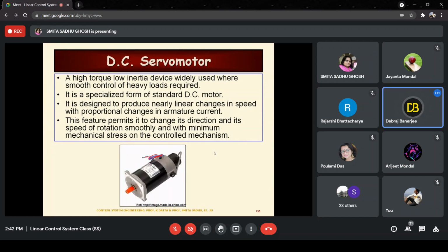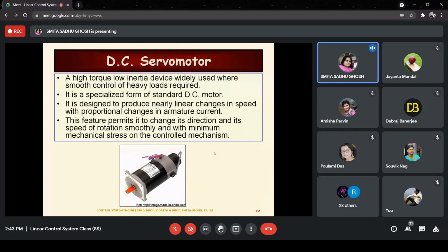Proportional to radius square. Yes. So if we want a lower inertia, we should typically make the radius big or small? Small radius. Yes, small. That's obvious, isn't it? So the radius we would want to keep small so that the motor has a lower inertia. But at the same time, the torque developed should be high.